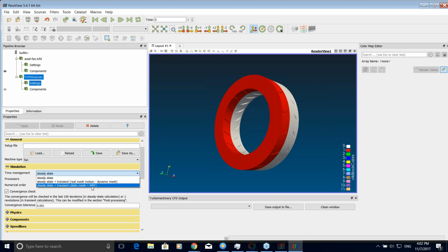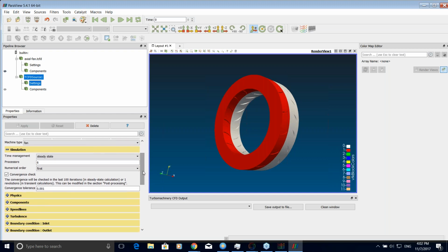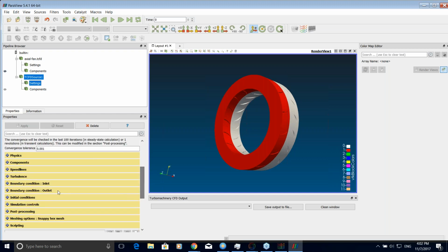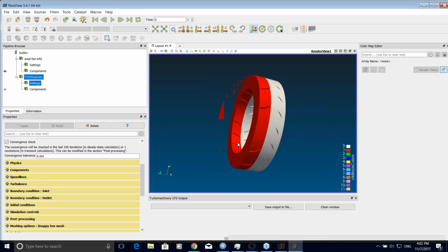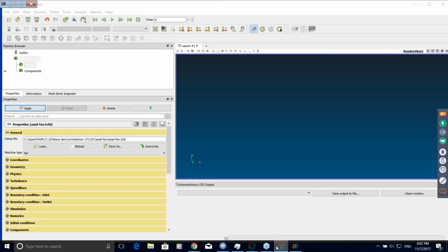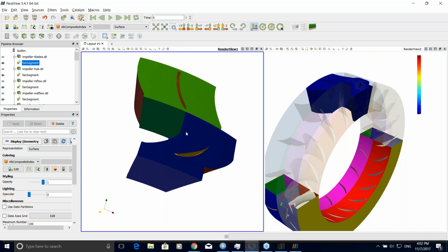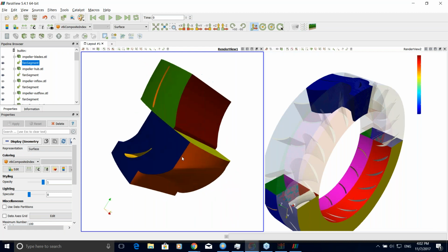So run simulation, and really a transient simulation using, for example, LES or the RANS turbulence modeling, or DES or something similar. And the second question was about the frozen rotor. Yeah, the frozen rotor can be applied only when you have full correspondence between the rotor part and stator part. It cannot be applied to the segment part, because as you can see, this interface is not connected fully to this interface.